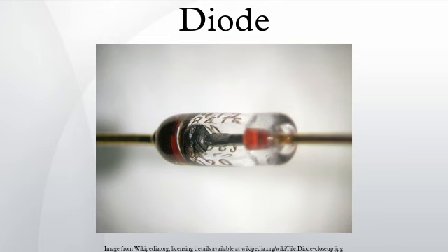Diodes are also used in electronic musical keyboards. To reduce the amount of wiring needed in electronic musical keyboards, these instruments often use keyboard matrix circuits. The keyboard controller scans the rows and columns to determine which note the player has pressed. The problem with matrix circuits is that, when several notes are pressed at once, the current can flow backwards through the circuit and trigger phantom keys that cause ghost notes to play. To avoid triggering unwanted notes, most keyboard matrix circuits have diodes soldered with the switch under each key of the musical keyboard. The same principle is also used for the switch matrix in solid-state pinball machines.